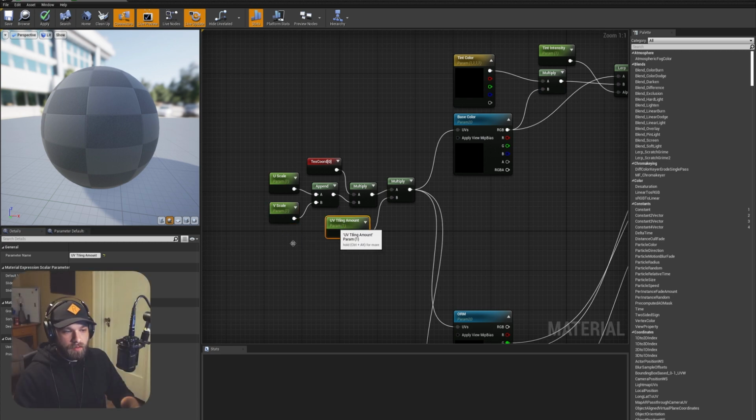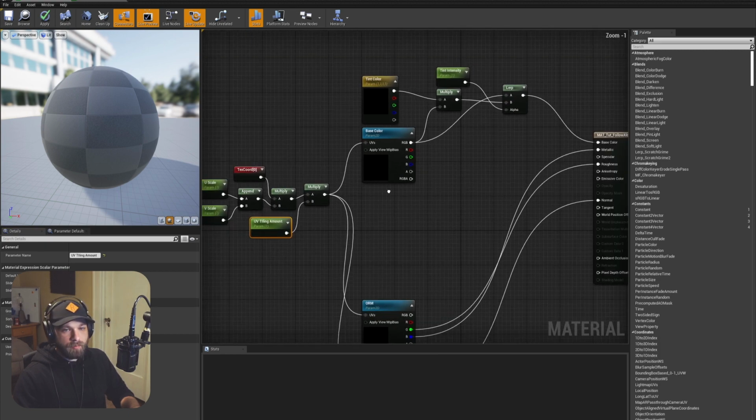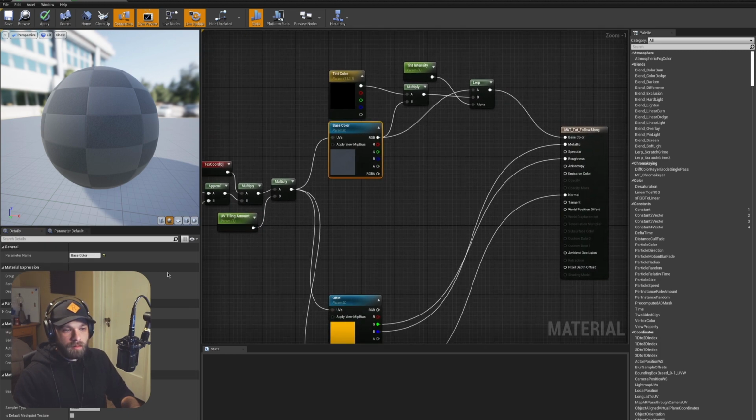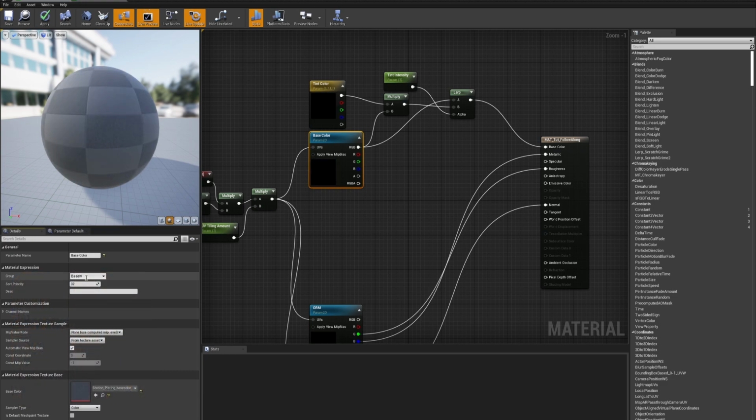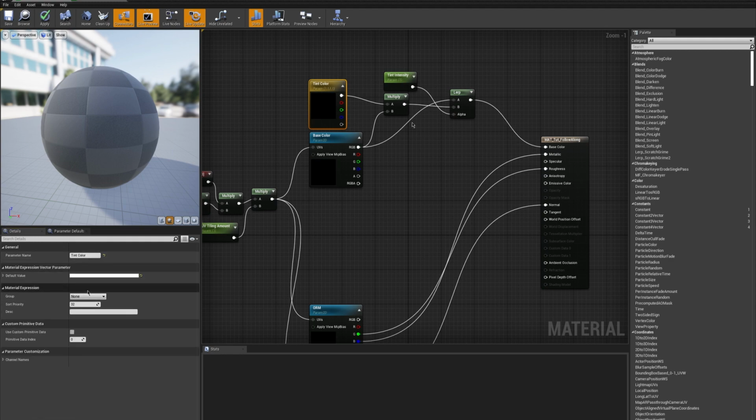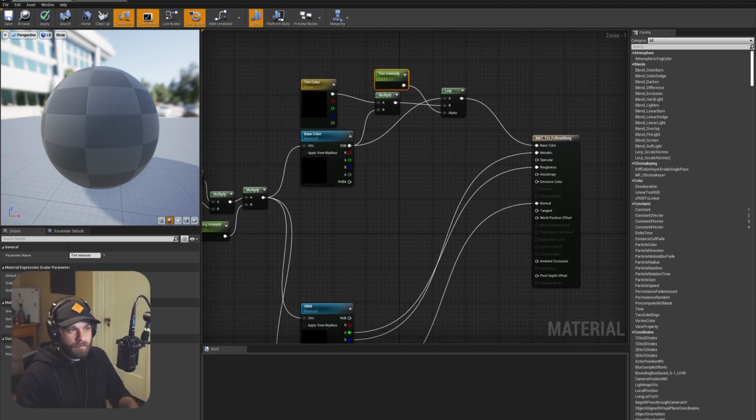And once you've typed it, you can just go ahead and go to the drop down. It should be there. So we've created a UV group. I'm going to name this one... actually, we're going to do this. We're going to do a group for base color, and we'll include the tint in that base color group, since that is the channel that it's affecting. And then we go ahead and save again, and we'll jump over to the parameters.